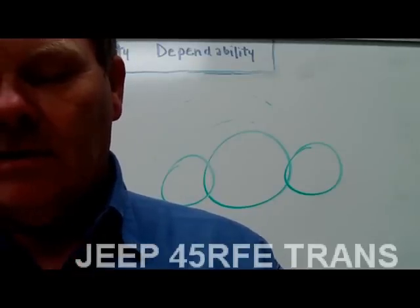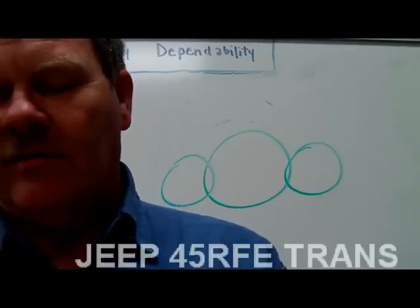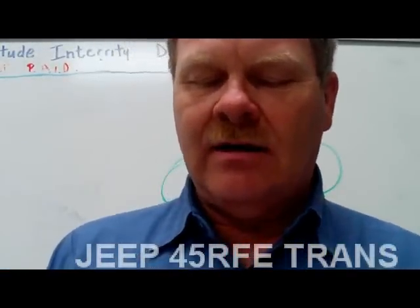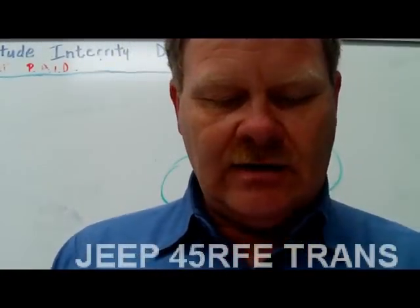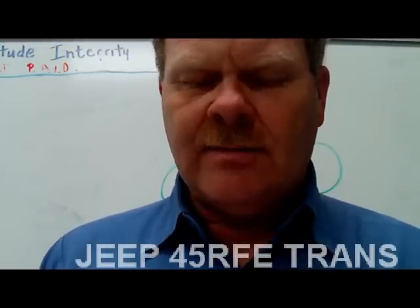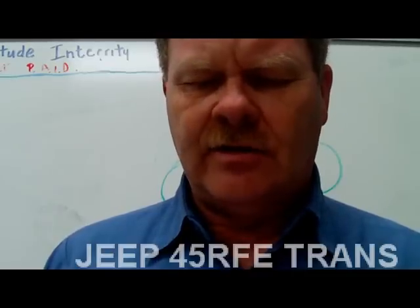You understand that? During some of your kick-down shifts, the 2 prime gear is obtained by employing underdrive and fourth clutches. When the gear selector is in manual low, the underdrive and low reverse clutches are applied. And there's a chart here that I can show you. As a matter of fact, I think this handout is in that computer over there, if the work study student put it in there.